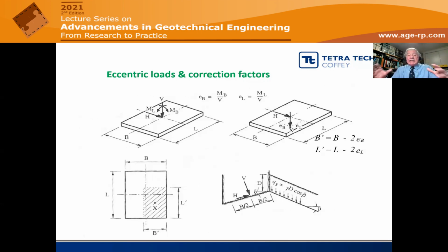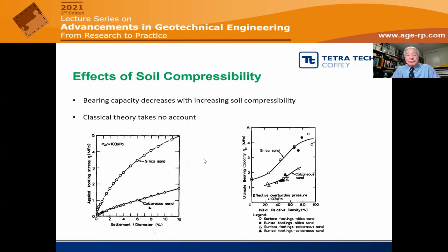And by just taking that reduced area as your vertically loaded area, you can get an indication of the bearing capacity of the eccentrically loaded foundation.